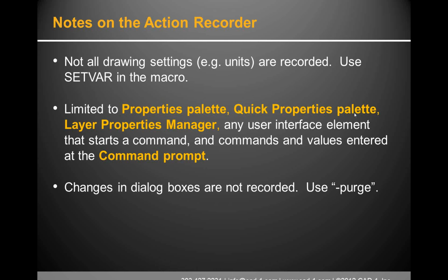Using the layer properties manager, we can record the step of creating the layer itself, and then continue on to use the properties palette and select all viewports, and have it automatically change all of those to that new layer. So you can use a combination of those.